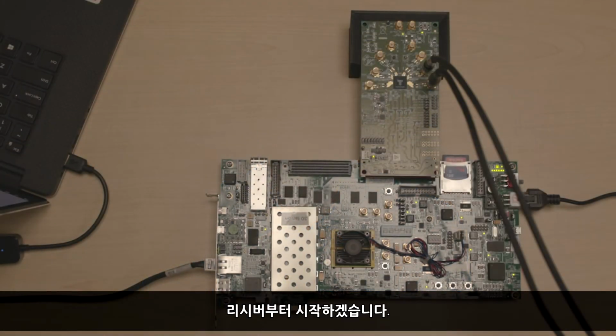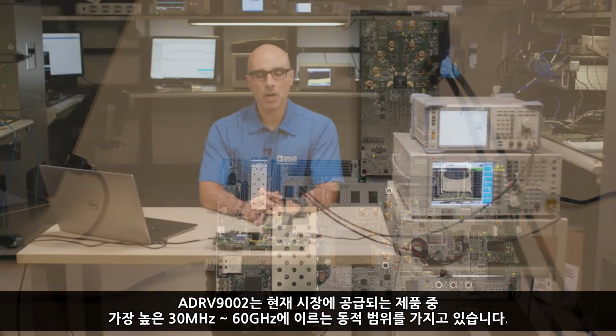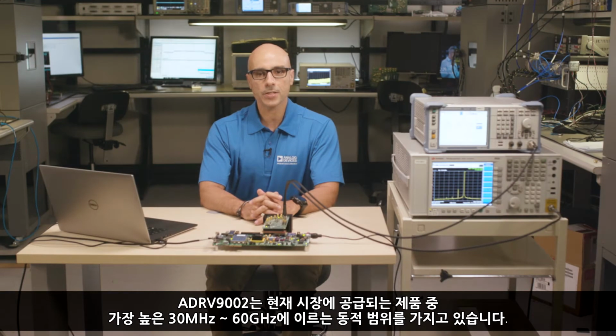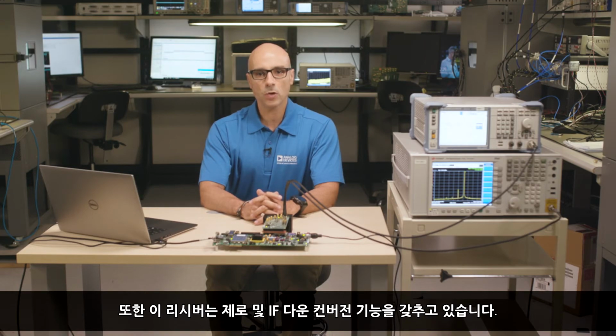So let's start with the receiver. The ADRV9002 has the highest dynamic range on the market today, from 30 MHz to 6 GHz. It achieves exceptional phase noise and blocker rejection performance. The receiver has both zero and IF down conversion capability.